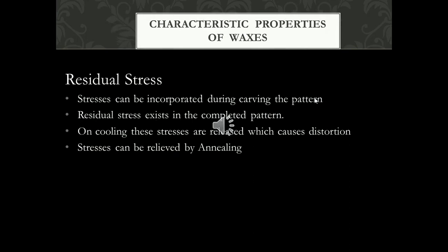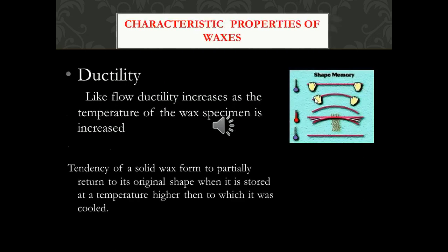Residual stresses. Now, this is another property. Whenever we are carving wax or subjecting it to different temperature changes, it tends to develop residual stresses within. These stresses are released, so we have to be very careful. We have to ensure that we do not carry out sudden heating and cooling of the wax, to prevent these stresses being incorporated and released. Waxes also have ductility, and this increases as the temperature of the wax is increased.